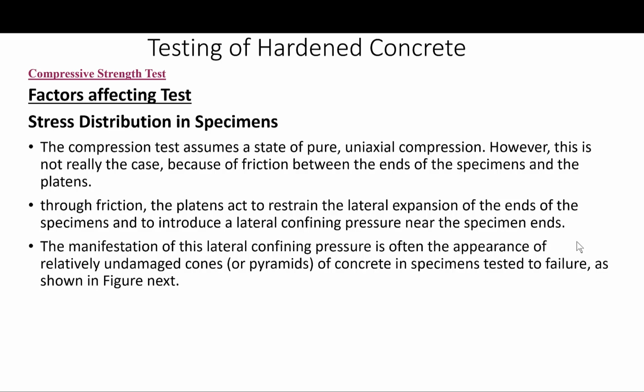If they were free to move, you have to keep that in mind. So through friction, the platens act to restrain the lateral expansion of the ends of the specimens and to introduce a lateral confining pressure at the end of the specimen.